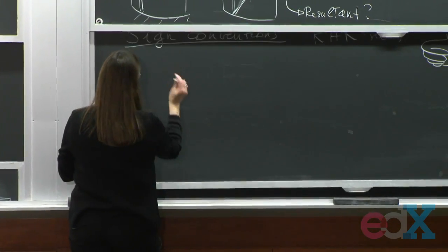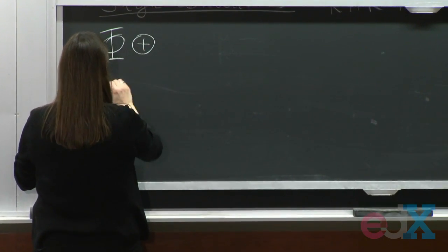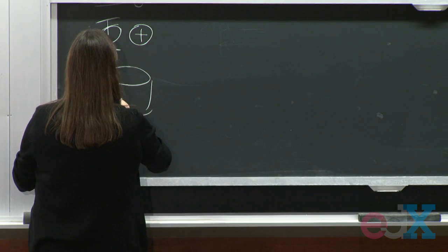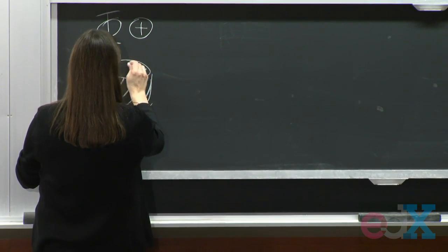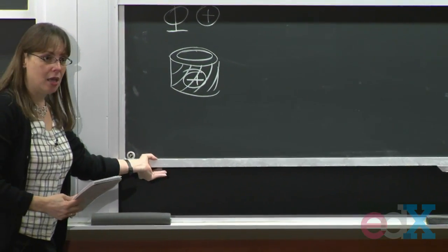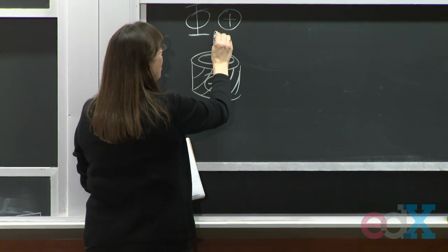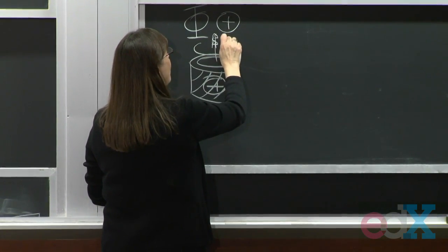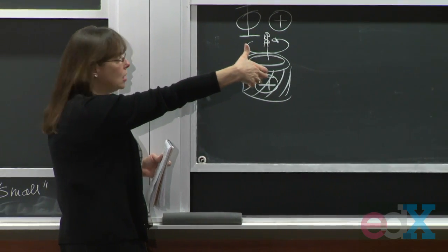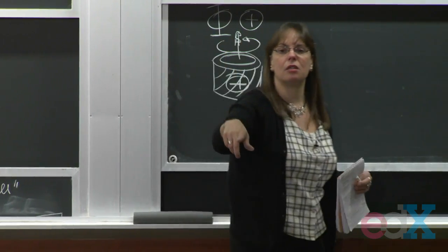So if you look at your angle of twist, an angle of twist is positive if something that had a straight line, once it's deformed, looks like that. So this is a positive angle of twist. Why? Because I went here, and if I draw the axis of this angle of twist, I had to turn it that way. Look at the way my thumb points. Out. You see?